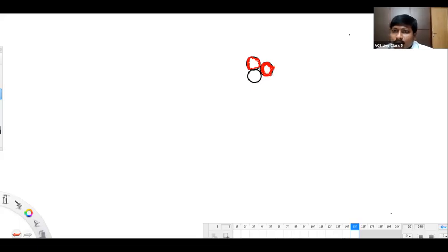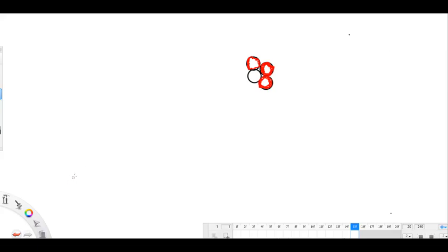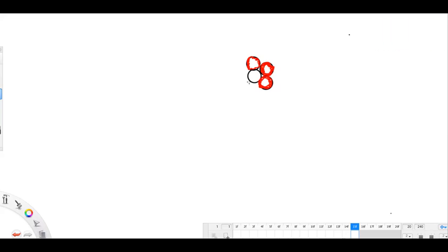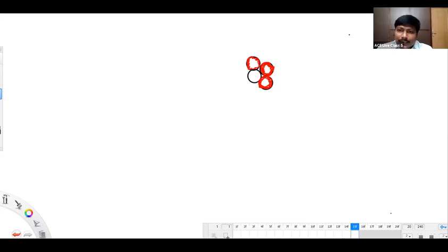Yes, sir. So, in that view, if you compare the solid conductor with this one, definitely the area through which current is passing is going to be increased. Understood the thing, what I said? Yes, sir. Clear? Yes. Do one thing. Take one solid conductor, show the current flowing area in the red color. Take the ACSR conductor, show the current flowing area like this with the red color.